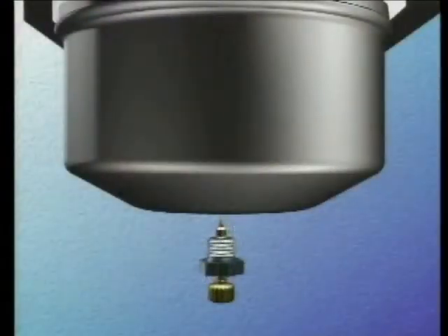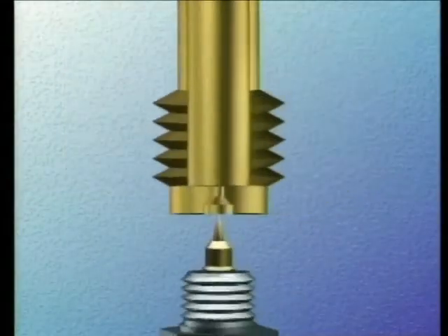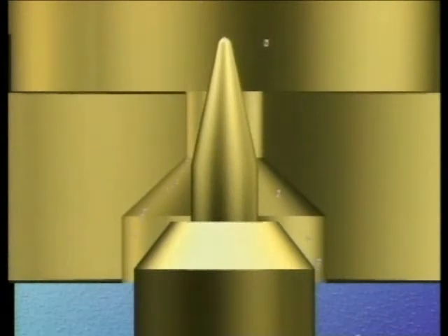Let's take a closer look at how those bubbles and vapor lock created problems in some adjustable jet carburetors. As the bubbles increased in number and size, occasionally one would lodge itself at the annulus of a jet or needle and seat. That bubble now takes up space, which would normally contain fuel, and in effect leans the mixture in the carburetor.